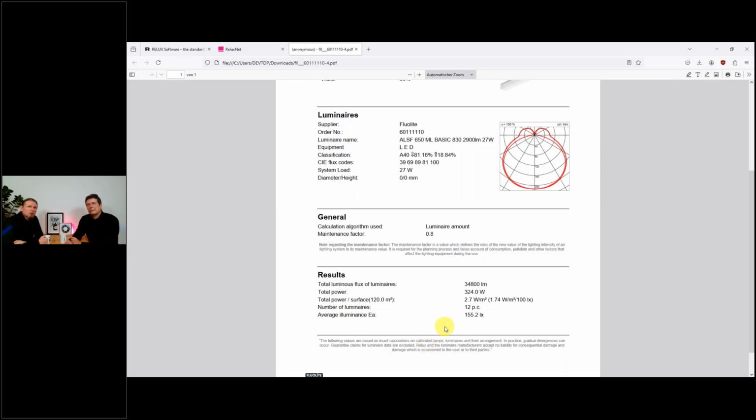It's also really energy driven. So you can think about it as just painting the energy of the luminaires on the task area, and then you have an amount of energy which you need. You have no homogeneous values here, no uniformity, no glare values. Everything which is part of a real photometric calculation is not included because of the method.